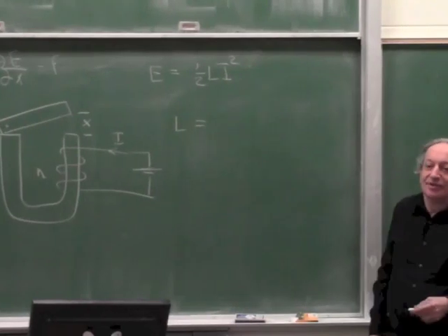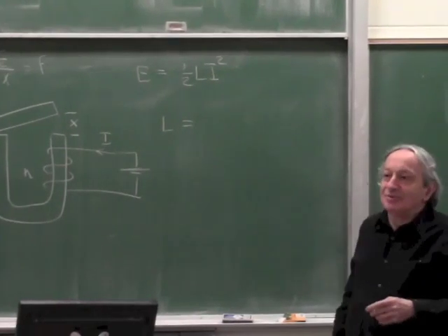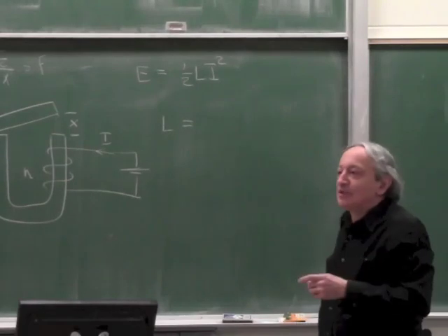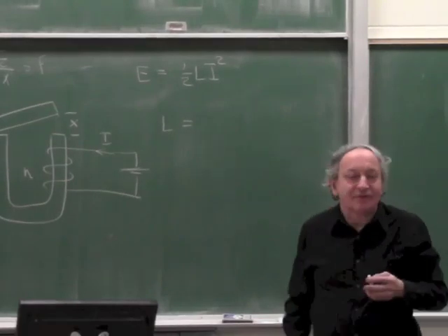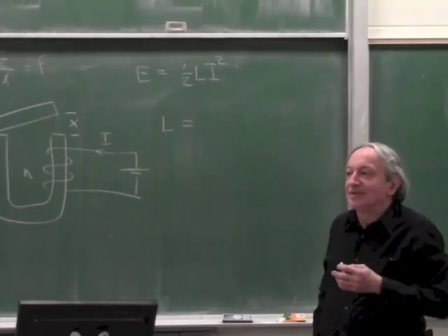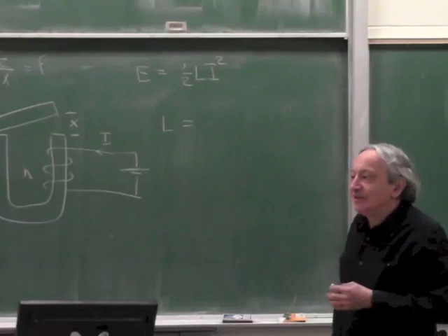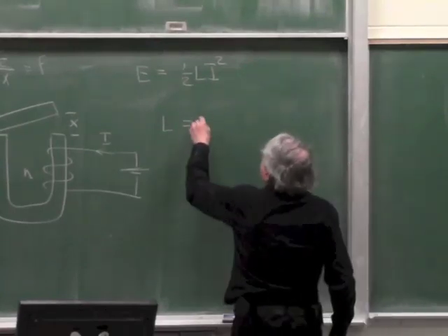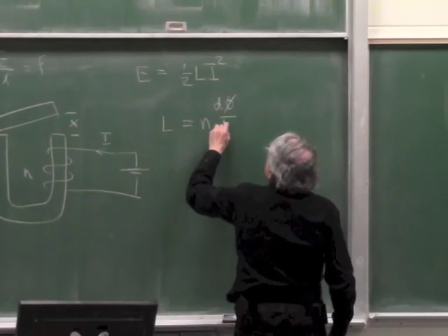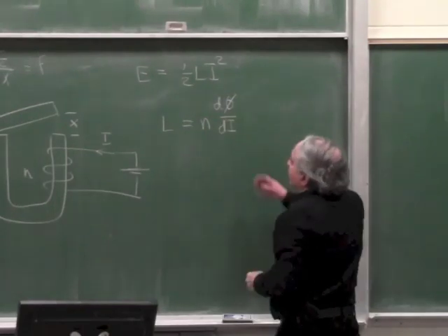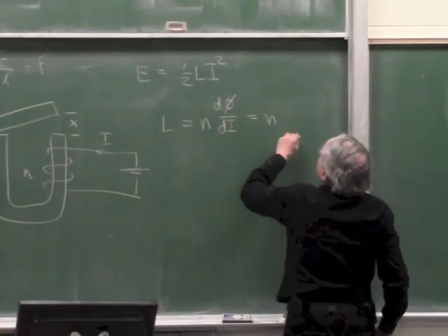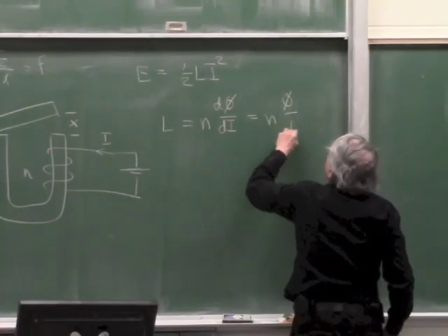That's a bit harder, because some of you never learned that. Does somebody know what's the formula for L for an inductor? It's actually a definition, not a formula. The definition of inductance is N delta phi over delta I, and if it's linear, since most inductors are linear, it is N phi over I.